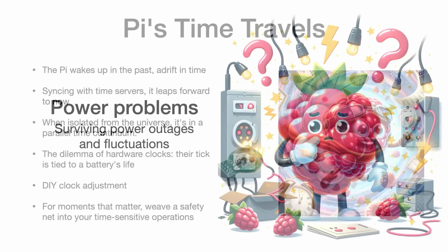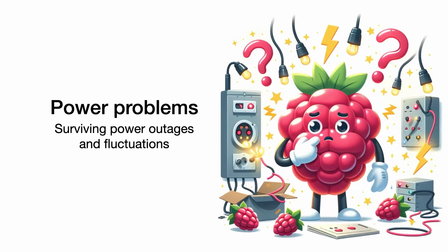Now, when you have a Pi in the wild, your worst enemy is power fluctuations. I had a slide originally saying that you need to pay attention to the power supply you buy, the type of SD card and everything. Well, I know that probably you've run into that. So the power outages and current fluctuations are your enemy. They can corrupt some files. They can freeze your Raspberry Pi, or even corrupt the OS, rendering the Pi unusable.